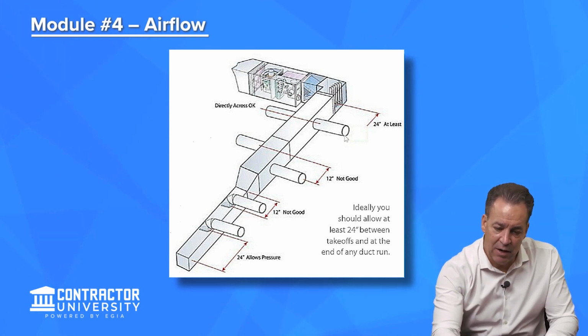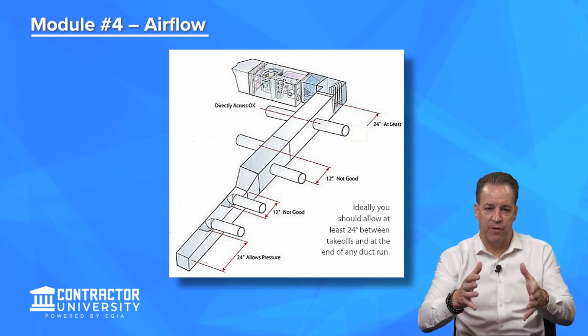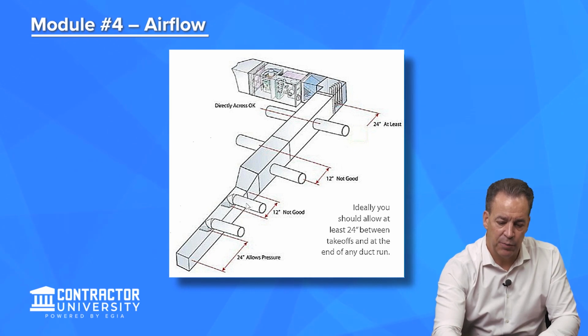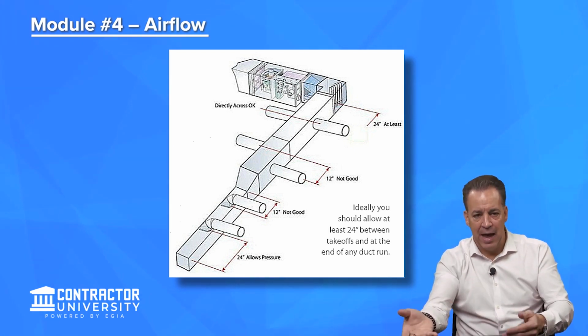And as you can see here, as we peel off 4 supplies, then we shrink down, so we maintain the velocity. Because air has left, the volume of air is less, and so with less volume of air, in order to maintain that static pressure, that friction, and that velocity, these supplies get air pushing out of them, not just dribbling out of them.